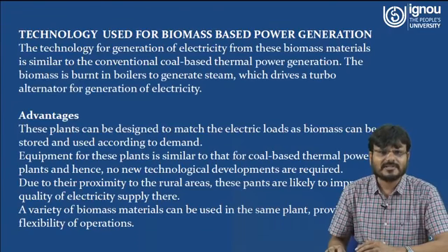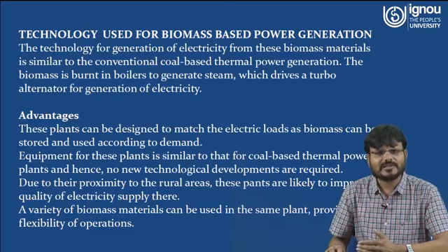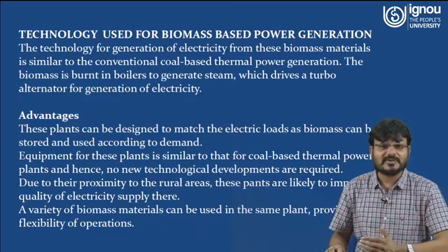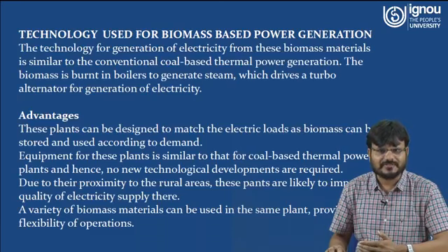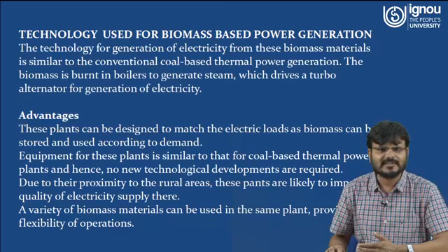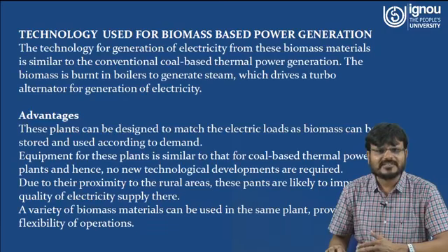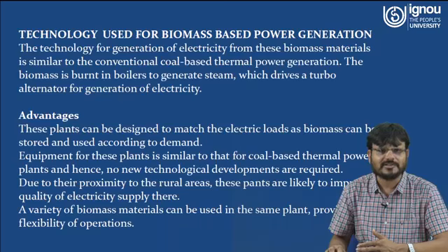Now we have to understand the technology used for biomass based power generation. The technology for generation of electricity from this biomass material is similar to conventional coal based thermal power generation. The biomass is burned in the boiler to generate steam, which drives the turbo alternator for the generation of electricity. And now, what is the advantage of this type of generation? The advantage is that these plants can be designed to match the electric load, as biomass can be stored and used according to the demand.